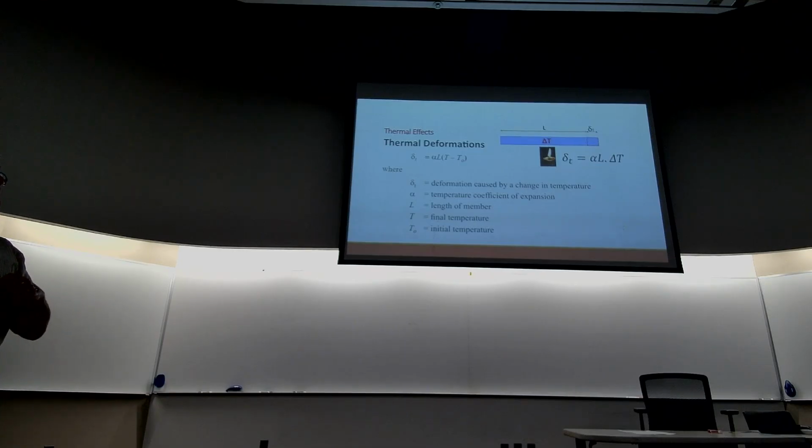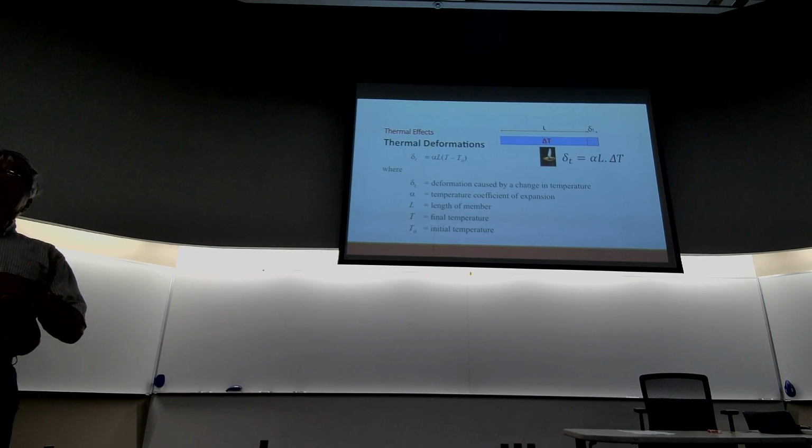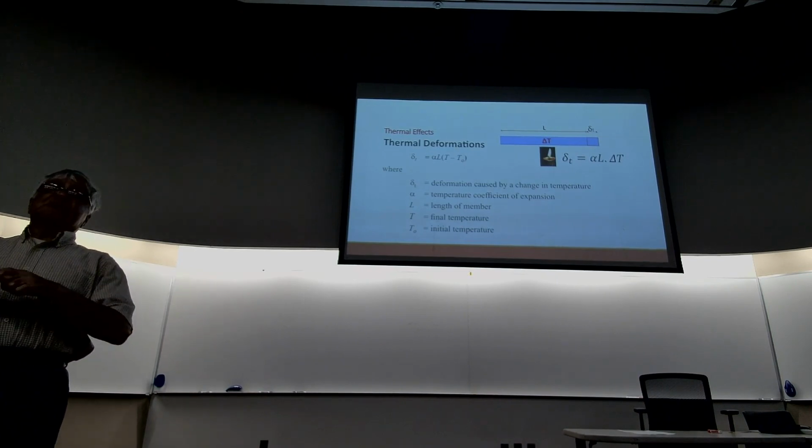But if you prevent the free elongation or inhibit that, then there will be stresses. Prevent and inhibit don't mean the same thing. Prevent means we don't allow any elongation, and inhibit means we allow some elongation, but not as much as what the material wants to do.